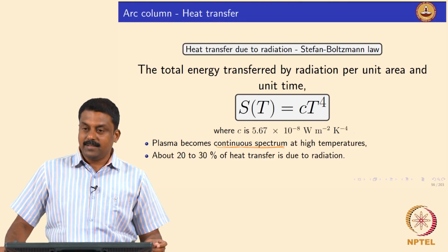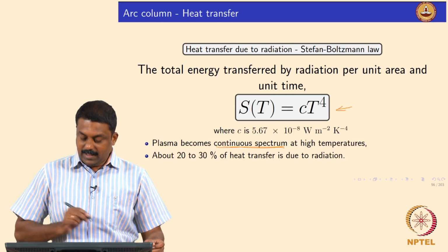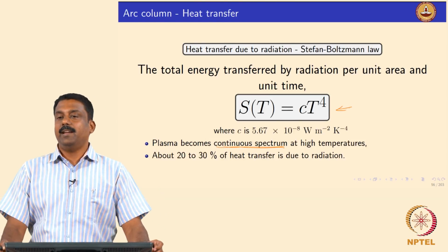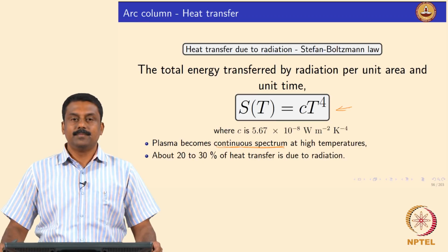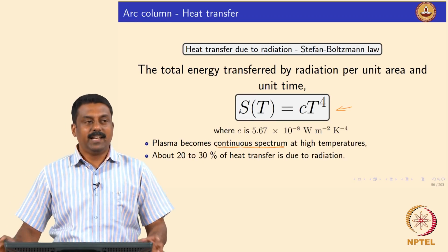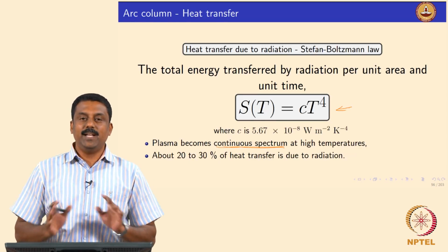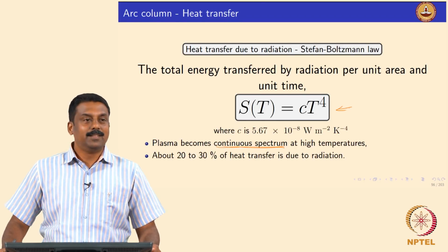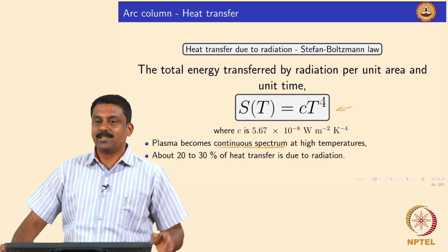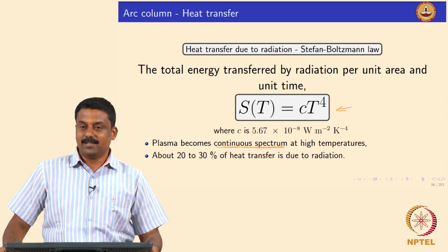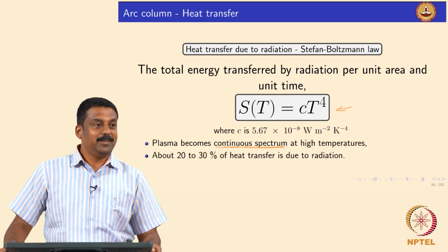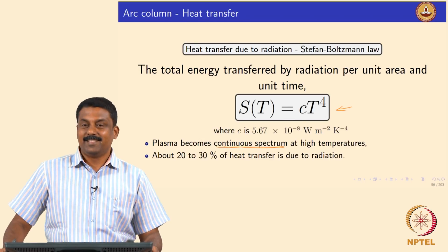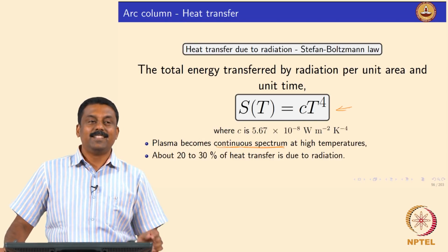So once you know that, we can calculate heat transfer by radiation. It is significant compared to conduction, about 20-30% is by radiation. Okay. So when you are welding, you just take your hand close to the arc. Okay, you feel heat, right? So that's being radiation.